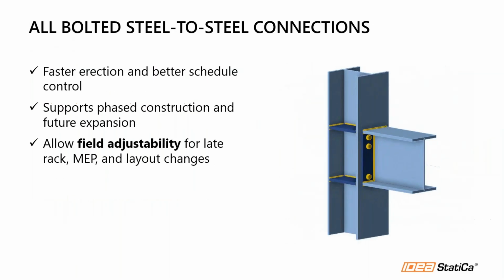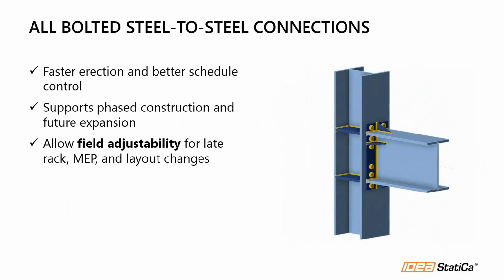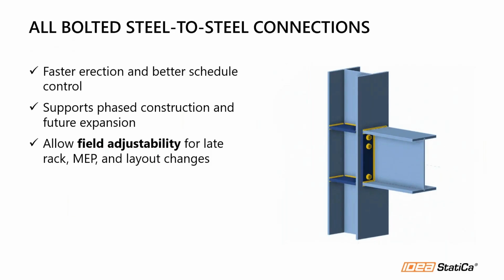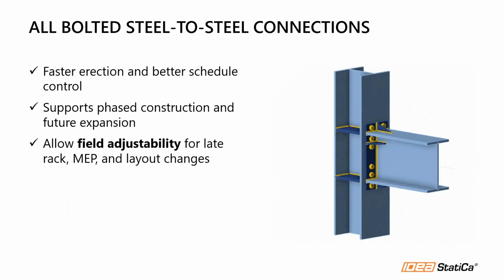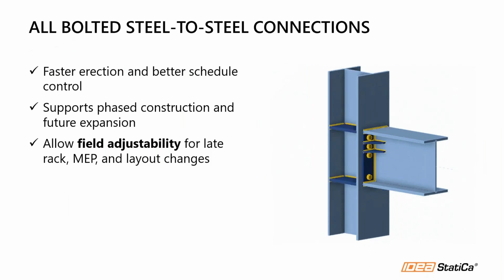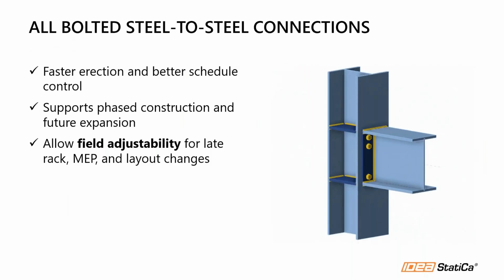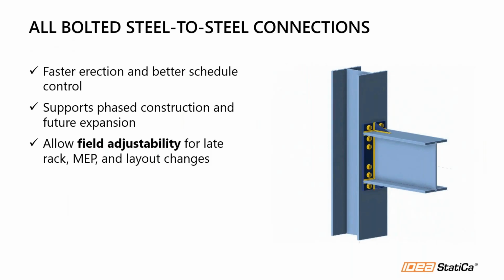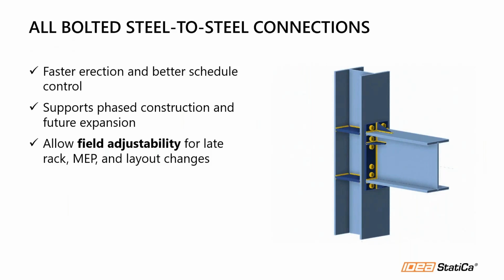All right, so the bolted connections here, they're able to reduce on-site installation time by being able to reduce additional steps, such as field welding or extensive detailing that has to be done for those connections, which in turn helps to keep fast-track projects on schedule. Data centers are also built in phases, so these bolted connections allow the expansion of new areas to be added without redesigning from scratch. And since late changes to rack layouts, MEP routings, or equipment loads can sometimes be common, bolted connections provide that flexibility to accommodate those changes without delaying your construction.